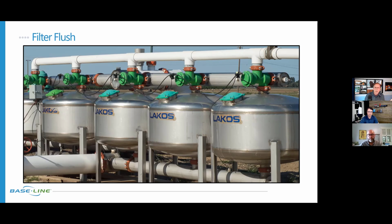So what happens now is we've dropped our pressure because we're flushing it off and reopening it back at the beginning of the system, and now we have poor coverage, poor DU on the rest of our system because we've released all this pressure. So how about we use a transducer, and we set up a filter flush based on pressure. When the pressure reaches a certain point, it's going to automatically flush the filter. And since it's on the same system, we're going to pause our irrigation. So now our irrigation is paused for the 5, 10, 30 minutes, however long it takes to flush the one filter or the 5 filters that we might have, and then resume irrigation once the pressure's back up to its correct point.